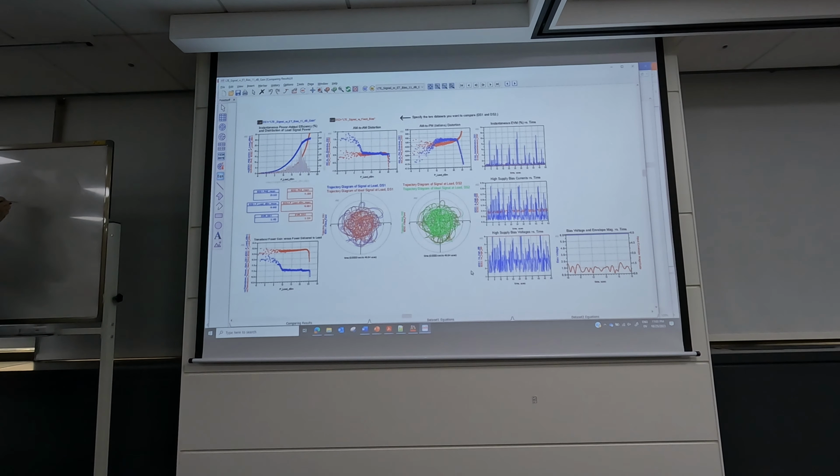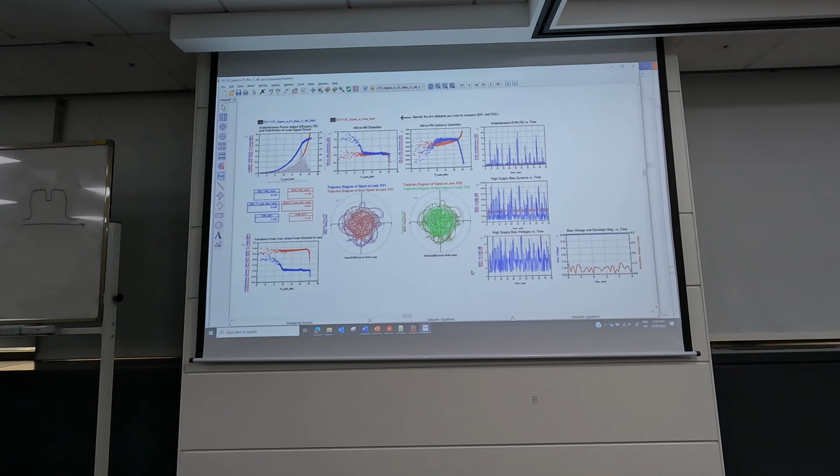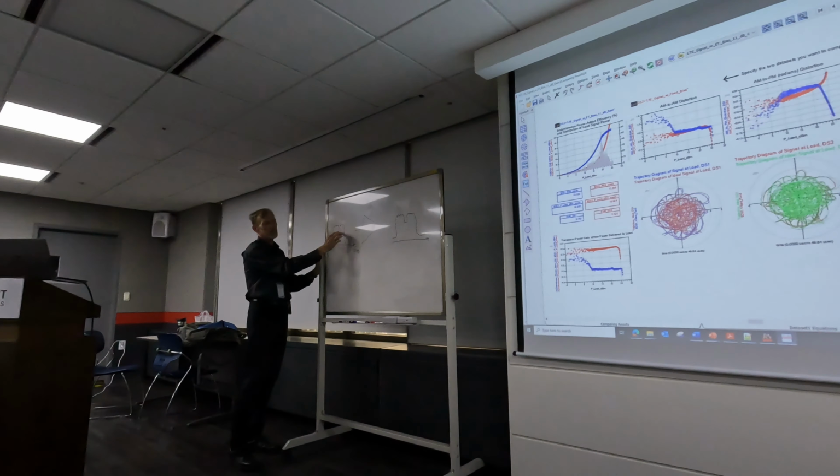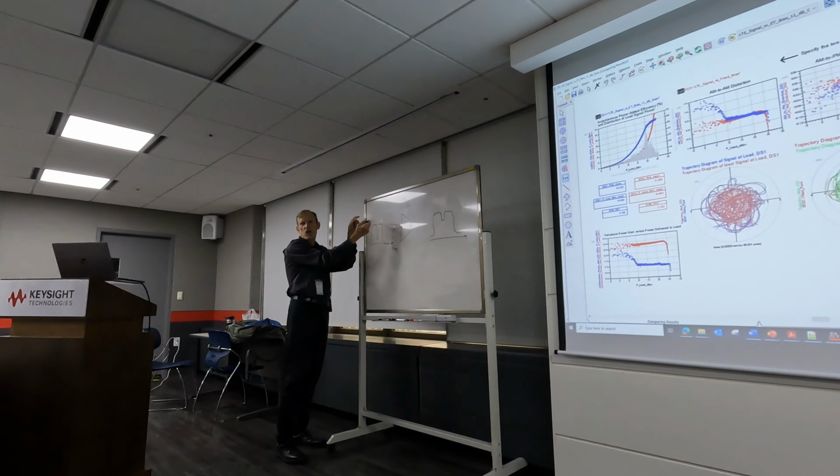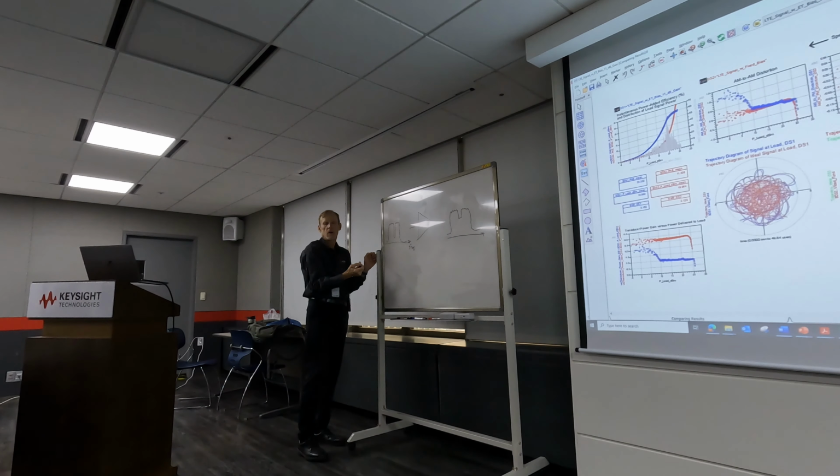And the output is the same, except due to nonlinearities in the amplifier, this notch in the middle gets filled up, effectively due to intermodulation distortion.